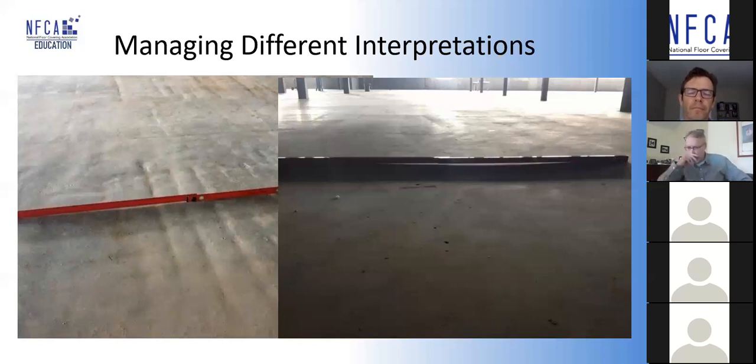You hit the nail on the head. All the things we're driving towards for floor preparation are to meet F710 once the concrete standard is established under E1155. Don't lean on E1155 to satisfy the floor cover. It does not do that. It has shortcomings. And keep in mind that whatever the concrete was measured at on day 3, even if it met a floor covering tolerance of say 5 millimeters or 3 millimeters in 3 meters, 6 months from now, it will not meet that tolerance. It will change.